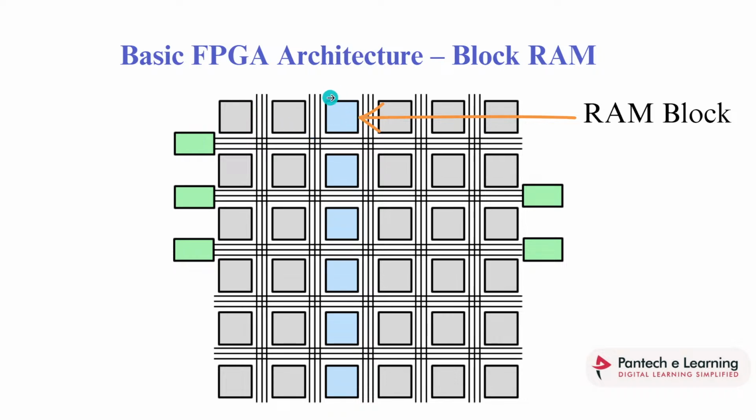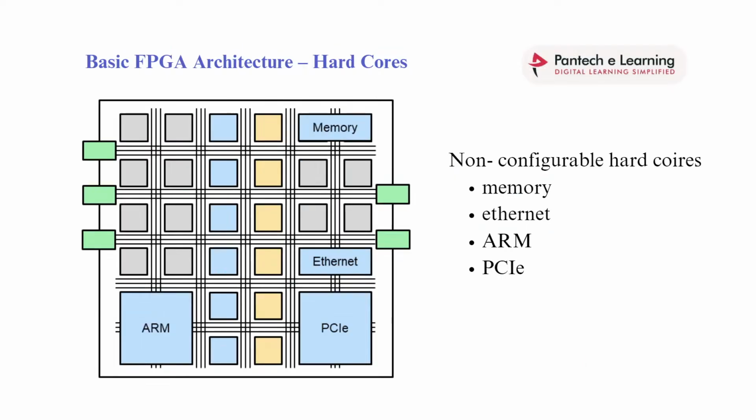It is fully based on HDL, hardware description language like Verilog. By using the Verilog code, we can change the logical elements in FPGA. This is a main advantage of the FPGA. We can use the logical elements however we want, so we can change the logical elements to RAM. And this is the whole concept of the basic architecture of the FPGA.